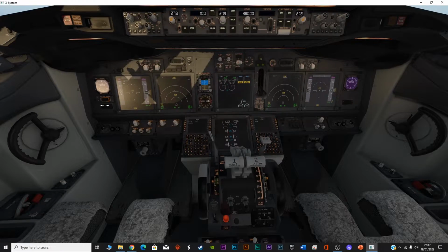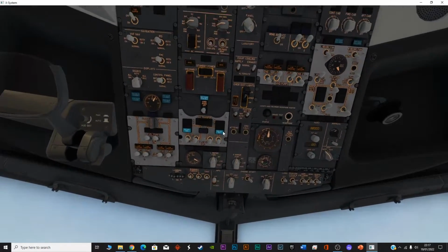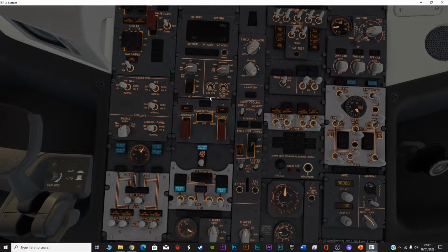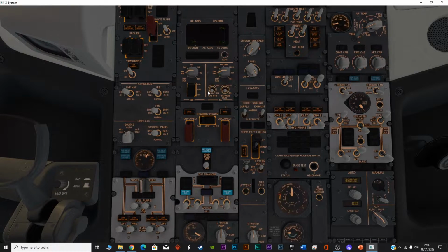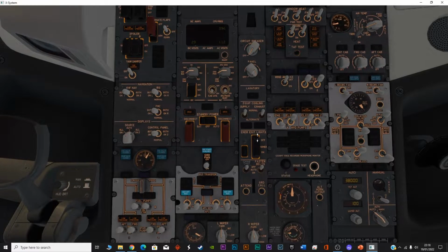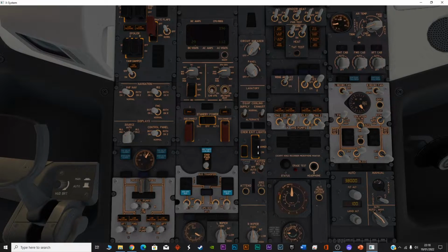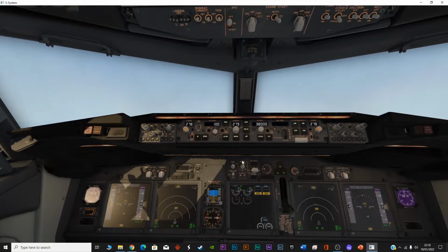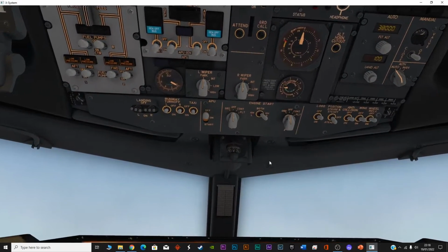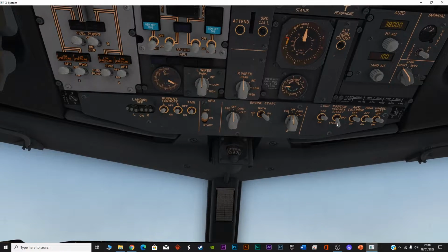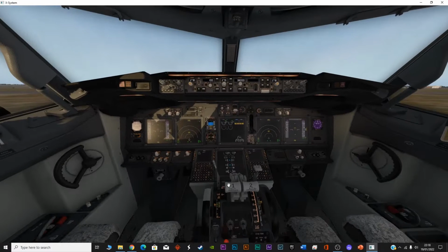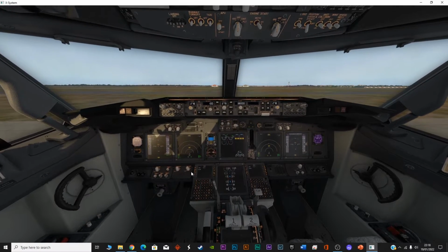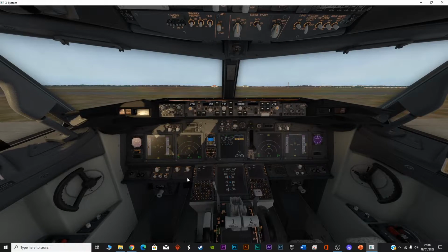Then there are two more controls that you have to look for: the cabin utility and the IFE pass. They should be on. Check this: emergency lights armed and covered. That's one of the checks. This is basically the emergency exit lights in the plane. Another thing that you have to do is set this position strobe to steady, which will tell the ground staff that you are in the process of starting up the plane. So that's why this indicator has to be switched on.